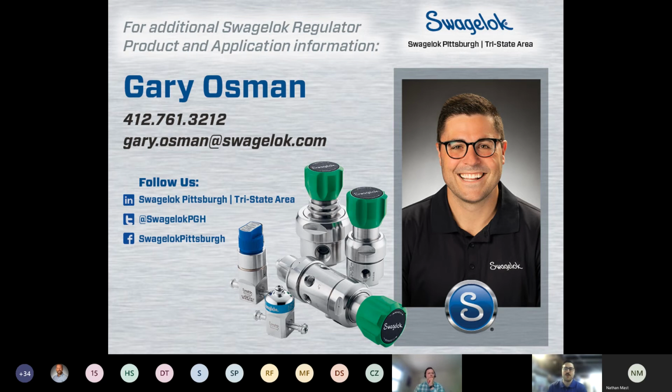And then this is an interesting question here. Can the venting options be incorporated in any way for relief, to substitute a relief device? It's a question we get quite often, and the mechanism by which the self vent works is really similar to a back pressure regulator or a relief valve. So it works on excess pressure, but the flow area is very small, and so the relief capacity is tiny.